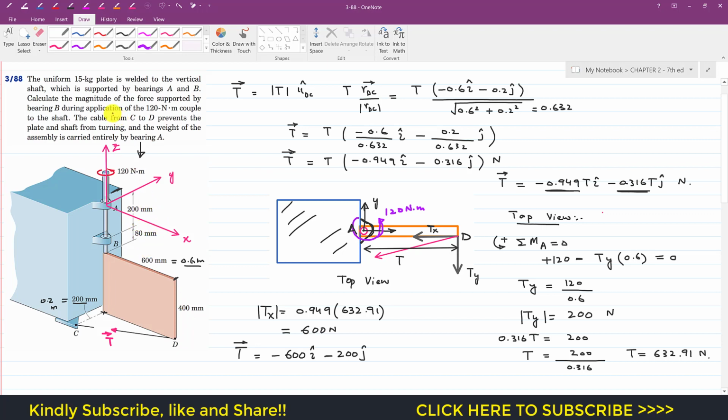Now in the problem statement we are asked to calculate the magnitude of the force supported by the bearing B. Right, so at bearing B we will have two reaction forces. We will have By reaction, which is going to act in this direction. This is the assumed direction. Let's say this is By, which is acting parallel to the y-axis, and here we will have Bx, which is going to act parallel to the x-axis. This is my Bx, and at A we will have reactions as well. Let's say here we will have Ay, and here we will have Ax.